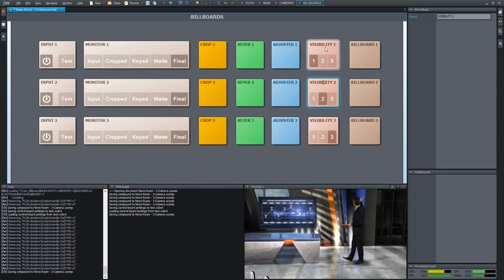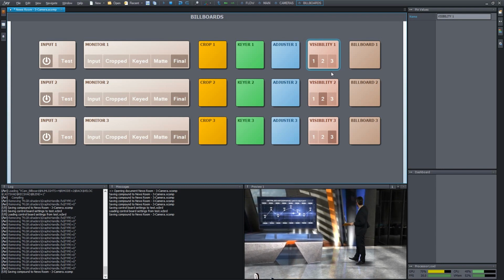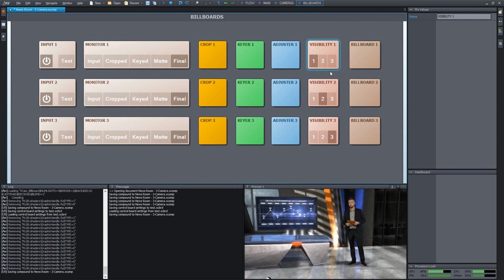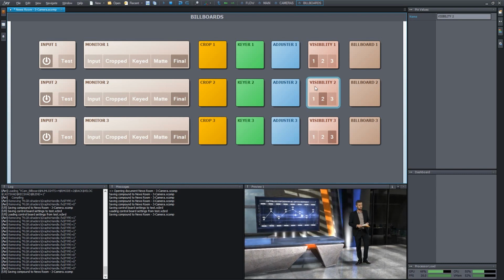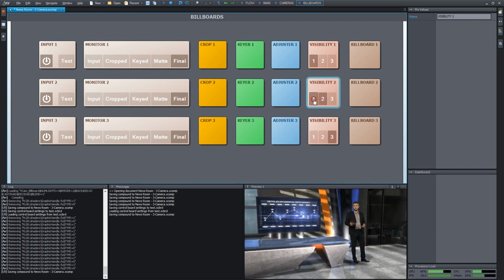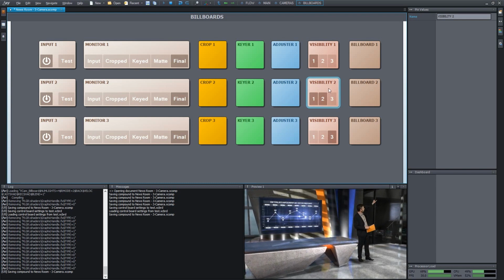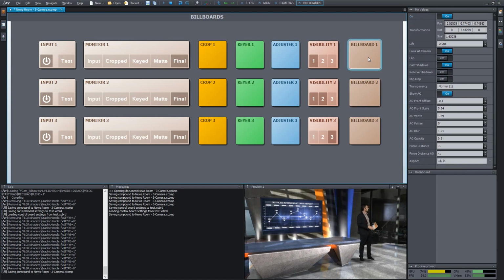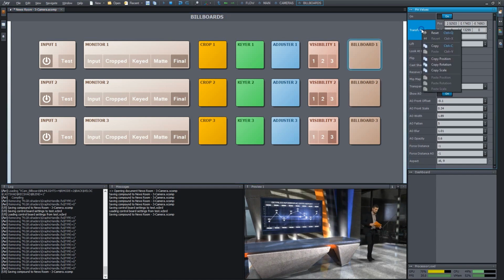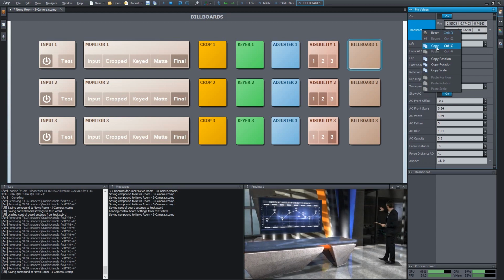With the help of this box, we can specify those virtual cameras which will have access to the specific billboards and make them visible. We can, for instance, decide that we want to make the content of Billboard 2 visible as well, when our camera 1 is active simultaneously with its own associated Billboard 1 content. Obviously, we have to move this Billboard 2 into the virtual space of our camera 1, where it can be visible.